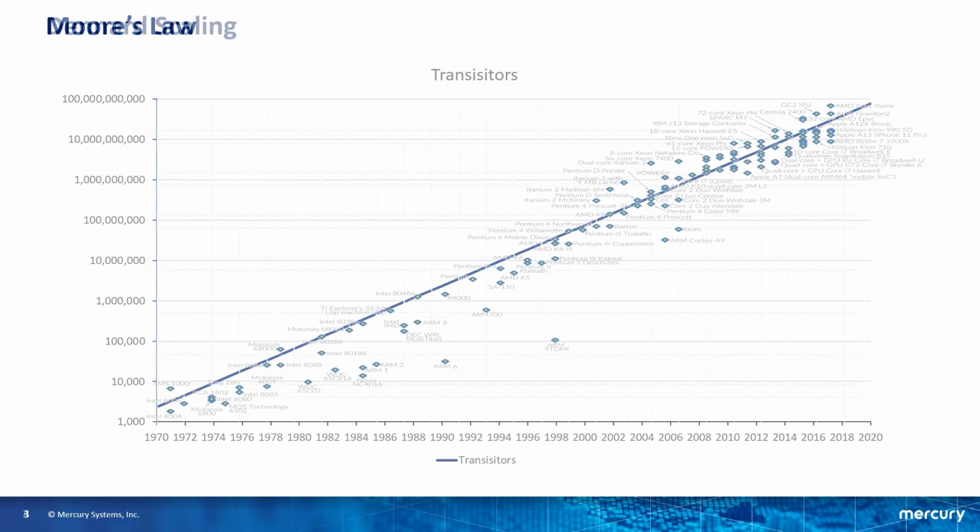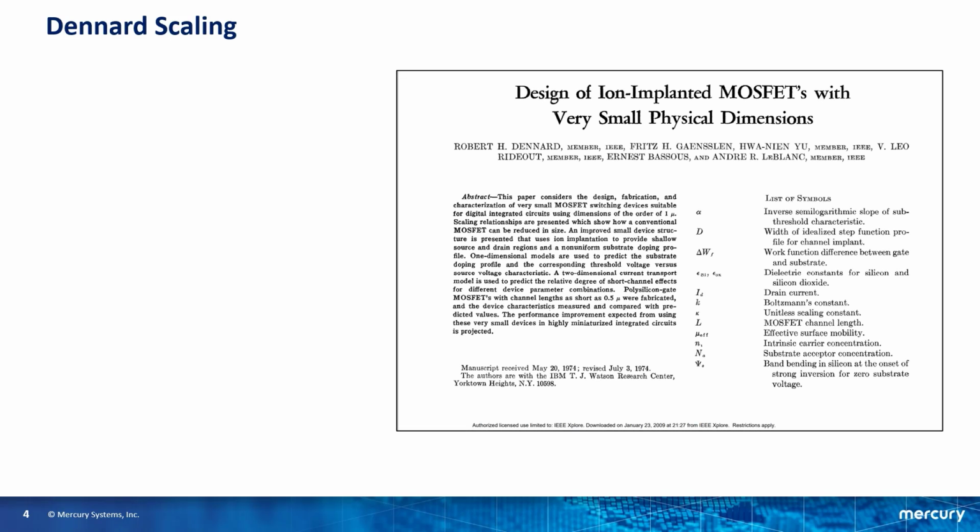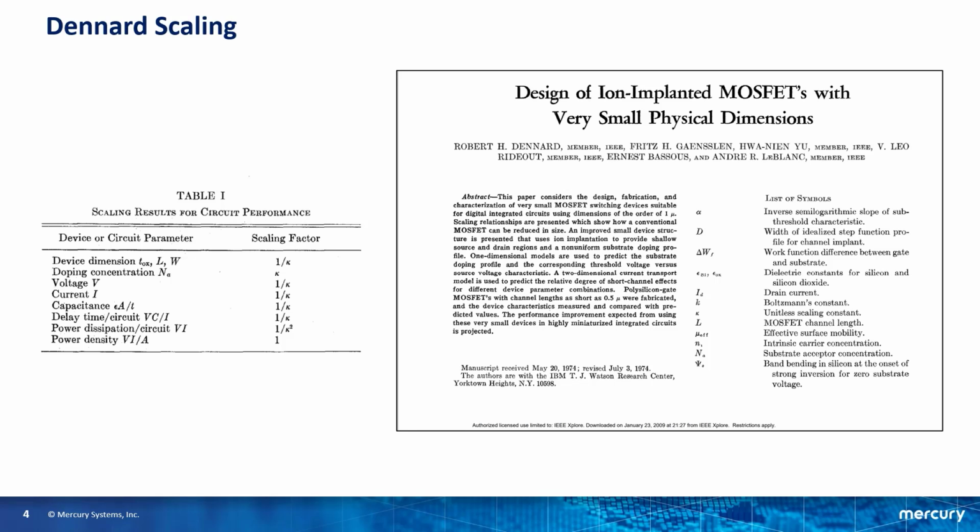In 1974, Robert Dennard wrote a paper detailing the benefits of processor node shrinks as the transistors themselves continued to get physically smaller with each generation. As a result of the shrinks, capacitance in the node was reduced due to the smaller area of the transistor, voltage was likewise reduced, and transition time was reduced, allowing the transistors to operate at higher frequencies. At the same time, power consumption per transistor was reduced, so as you double the number of transistors in a given physical area, the power requirement stayed roughly the same to operate twice as many transistors in that same physical space. Cost per transistor was also reduced with each node shrink.